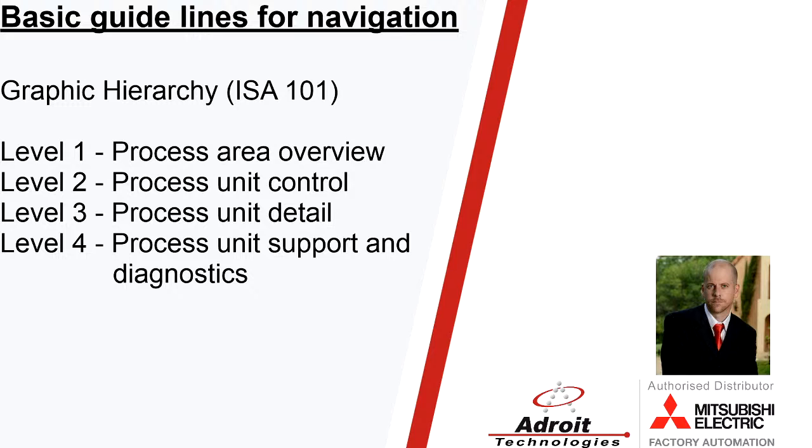And then obviously we get to our level 4, which is typically support and diagnostics. Level 4 is not something that you'd really go into unless there's a problem with the piece of kit that you're trying to view. So the VSD is giving us an error code maybe. Maybe we just want to notify the operator at the overview, listen, there's a problem on this particular control unit. We can look in the control unit and say, yes, there is an error here. And then obviously we can move into the details and then the support and diagnostics area.